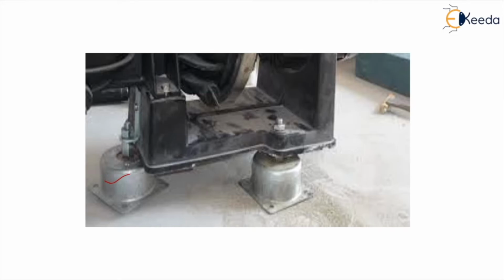Now, whatever equipment we are using for mounting will have at least one natural frequency. There may be more frequencies, but let's assume there is one natural frequency. In case the disturbing frequency of the machine or the system coincides with the natural frequency of the mount, what will happen? The vibrations will get amplified. The condition of resonance will be there. So while designing a vibration isolator or a mount, it is always required that the natural frequency of the equipment should be much less than the disturbing frequency of the system or the machine.